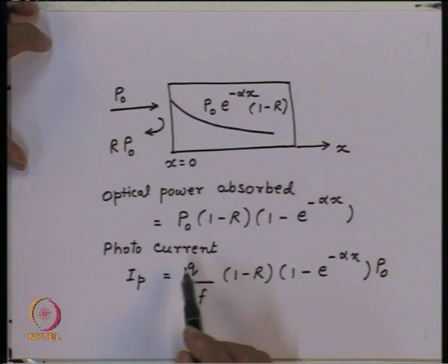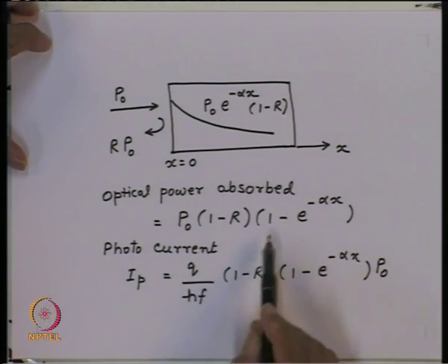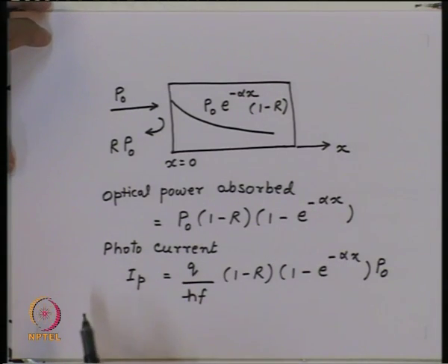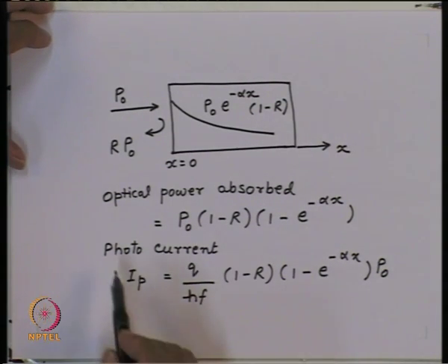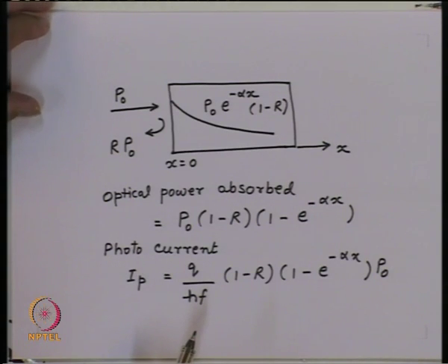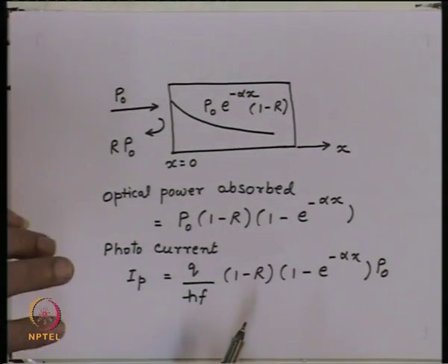And if you could collect the carriers generated by this photo absorption, then we get what is called a photocurrent. So, here we are saying that when a photon is absorbed inside a material, essentially a carrier, an electron hole pair, is generated, and if you create a mechanism by which this electron hole pair can be collected, a current will flow in the external circuitry, which we call the photocurrent.